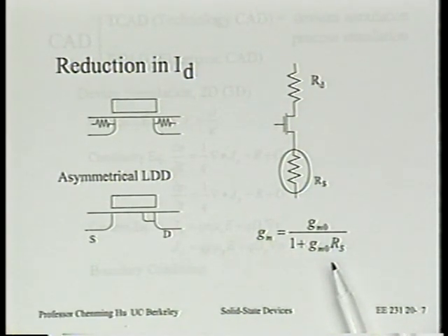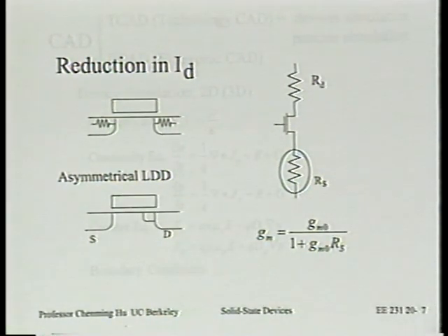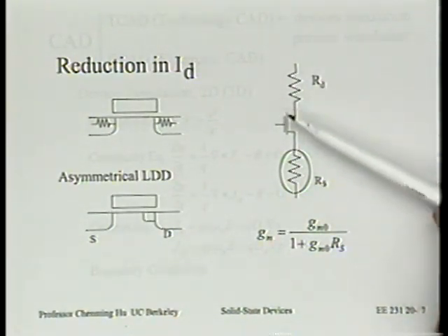Well, first of all, those are interesting questions. Not a bad idea, by the way, actually. Some companies deal with special cases, where they have just one transistor that won't hold a particularly large voltage, and hot carrier is a problem. I actually recommend just adding an external resistor. It's a very good solution, no problem. First of all, you want to add a resistor on the drain side, not the source side, number one, right? And then the question is, how much area is it going to take for you to add a resistor?